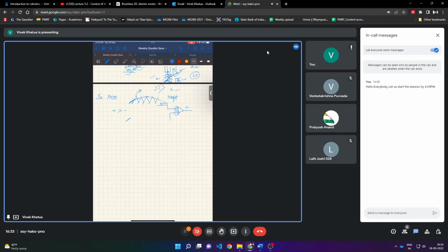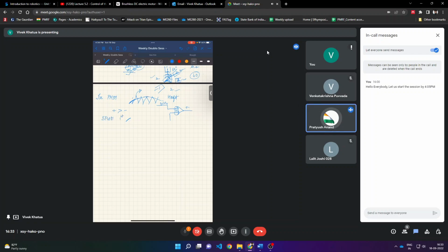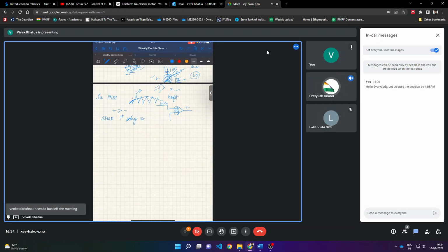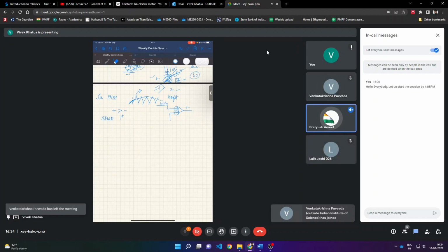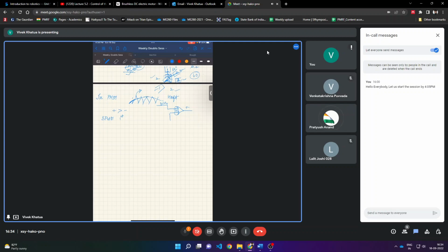So your question is that in SPWM, the reference was a sine wave, right? No, my question is that whatever reference we are taking against the triangular waveform is a curve, the upper half of the sinusoidal waveform. Is that coming from varying the pulse width, or is it another one?